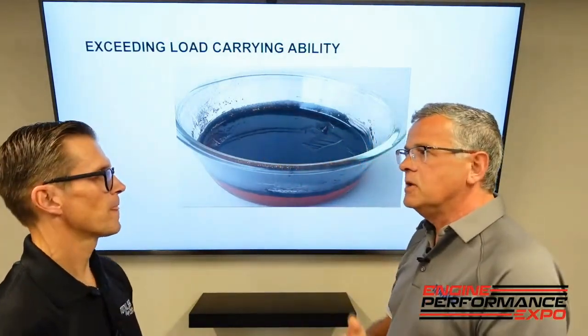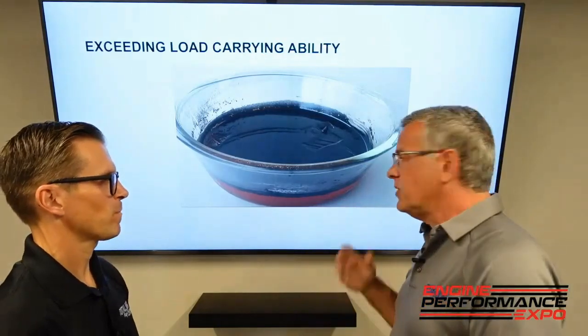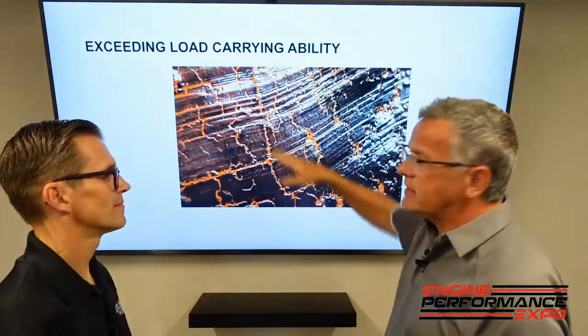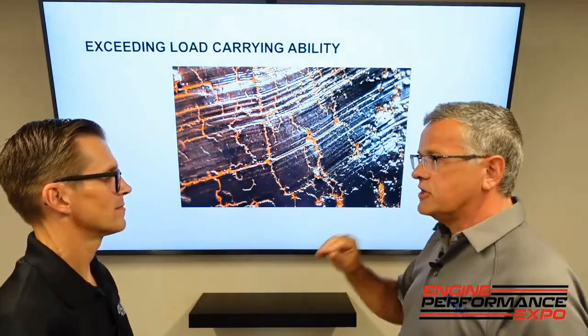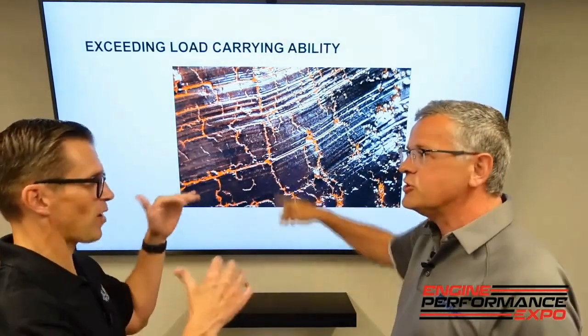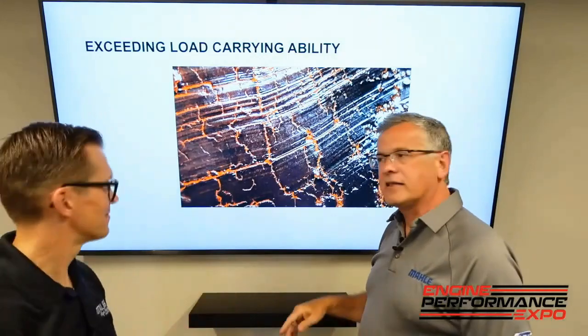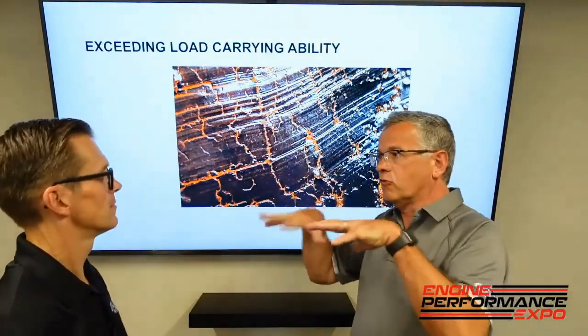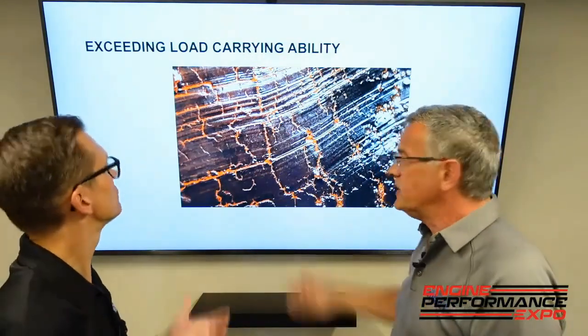Put it in the engine, and torsionals happen. Everything happens, and you end up with that fatiguing. Basically, what happened is your Jell-O shook. Yeah, the overlay's cracking because the Jell-O's moving. Exactly. So once the Jell-O starts moving, you get these fatigue lines in your overlay, which is exactly what you're seeing on the fatigue. Got it.